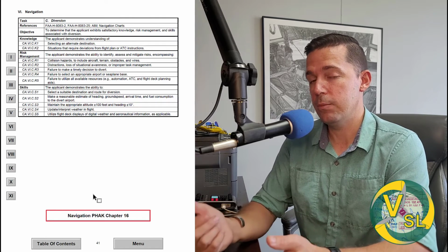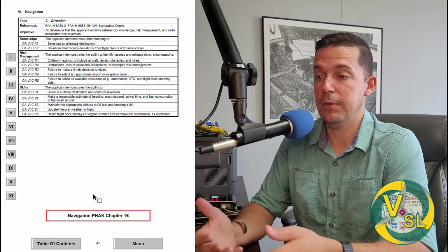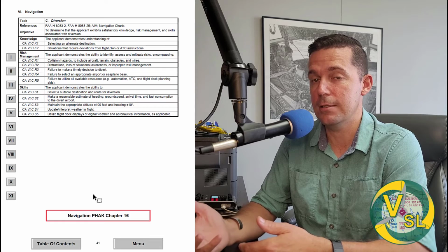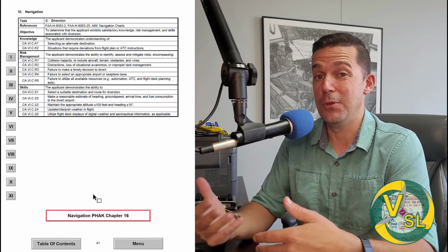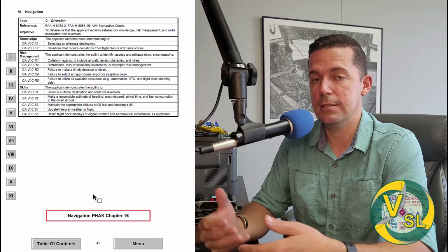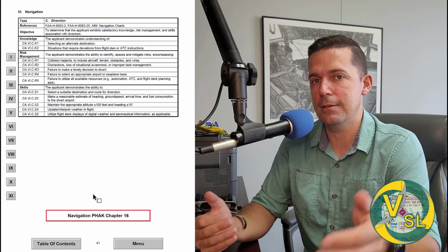They have the waypoint information where you can pull up weather if the plane's equipped. Even if the plane's not equipped with weather, you can pull up waypoint information to find frequencies for ASOS. If it's an airport that you don't know the ASOS to, that's a quick way to find that. You can find runway lengths and distances, and the altitude of the airport. Some critical information is in that 430.